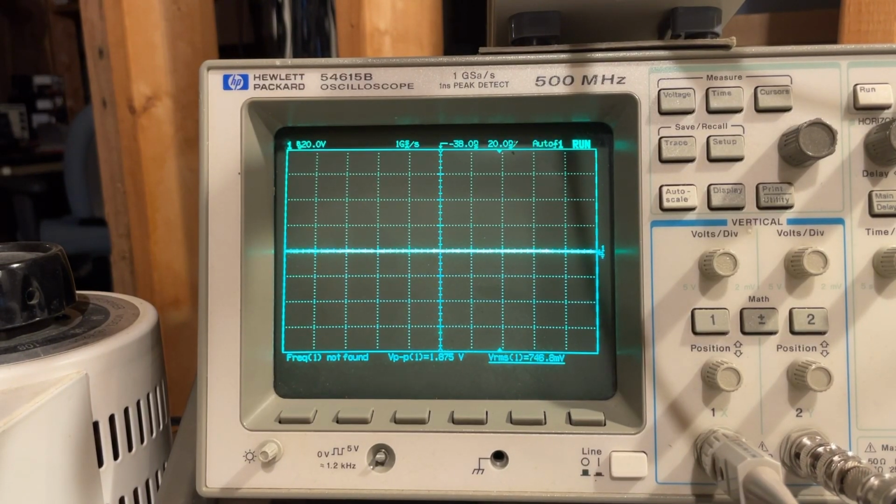So we'll be looking at the RMS output voltage and then just applying simple Ohm's law. So it would be ERMS squared over 50. That would give us the output power in watts. And we can compare that to the watt meter. And all of this is into a 50 ohm dummy load, of course. So let's go ahead and power it up.